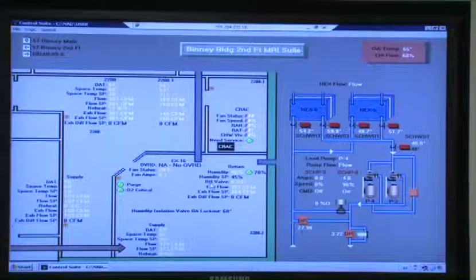I was told that you're not worried about this flooding? The statement is pertaining to humidity, or the humidifier, this system. Right now the humidity inside the space is 50%, the set point is 45. So right now the valve would be closed, because based on set point to humidity.